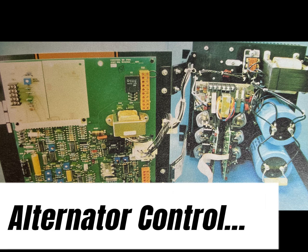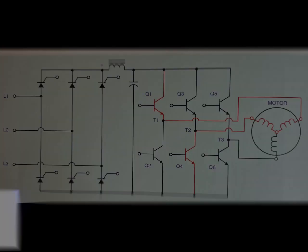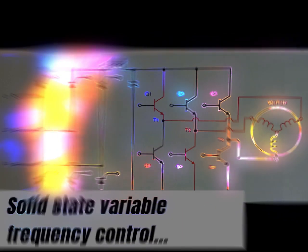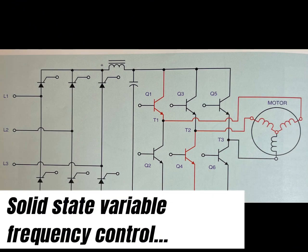Alternator control. One method of producing variable frequencies for operating induction motors is with the use of an alternator. In this arrangement, some type of variable speed drive, such as a DC motor, is used to turn the shaft of the alternator. The speed of the alternator determines the frequency of the voltage applied to the induction motor.